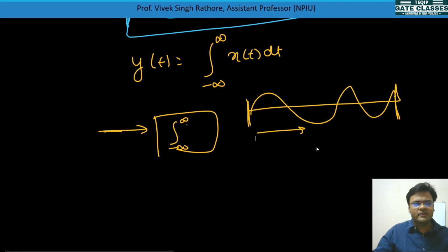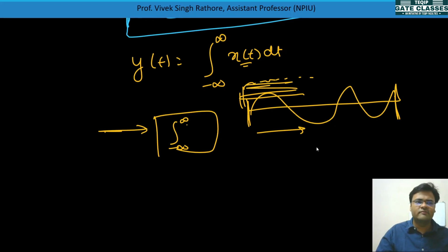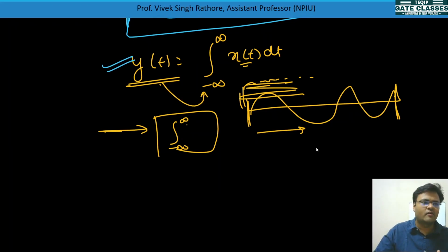See, if it is dependent upon the present value, it cannot add. If it is storing some value, then only it is adding, na? Means from minus infinite the values are added and then the output is coming. So ultimately these values were being stored somewhere. So that is why yt is dependent upon the storing element, and that is why this type of systems are called dynamic systems.